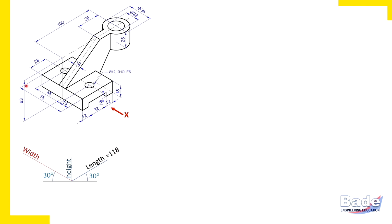Now overall width. With reference to this position of the observer, this is the front side and this is the back side. From front to back, extreme front surface to extreme back surface, the length is given as 75 mm. So the overall width of the object is 75 mm. Now check the dimension vertically.